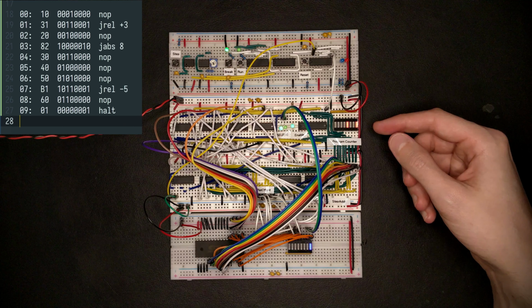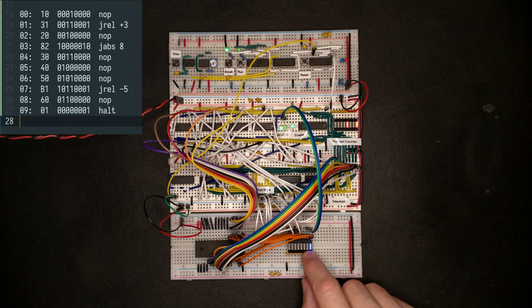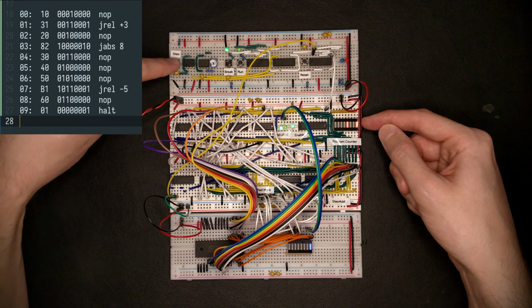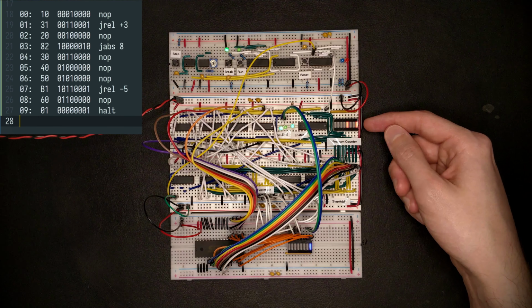And this instruction is a halt, which is a pseudo instruction. And all a halt is basically a relative jump with an offset of 0. So it's continuously jumping to the current address, basically making the processor stuck in a loop. Let's see if that actually works. So we have the 0 up here, which is basically the jump offset. And the 01 down here indicates a relative jump mode. So if I hit the step button, the program counter should not move. And nothing happens to the program counter.